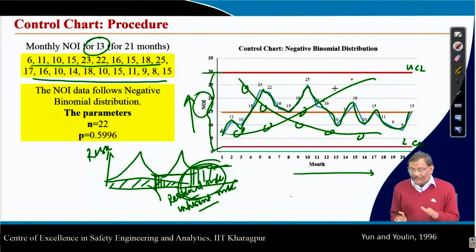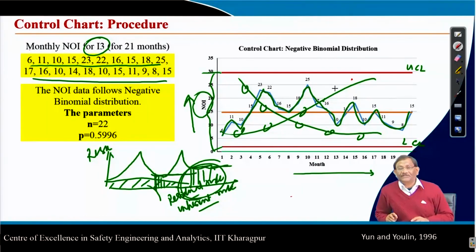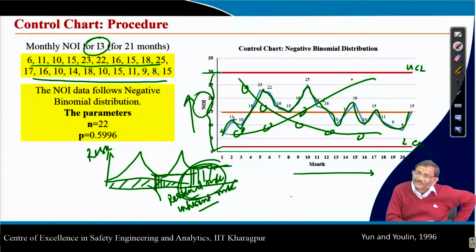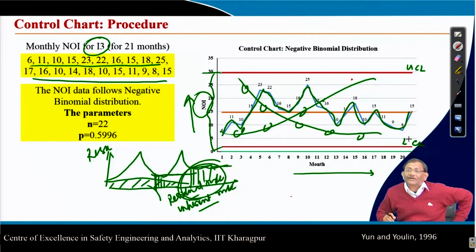So that means you first set the lower and upper control limits, the range within which this particular variable's values will lie, from the common cause point of view, because it is almost inherited in the system, based on design, based on your practice, based on your day-to-day operation, all the system components collectively. This is the overall common behavior of the system. Identifying and calculating the UCL and LCL is a real task also.